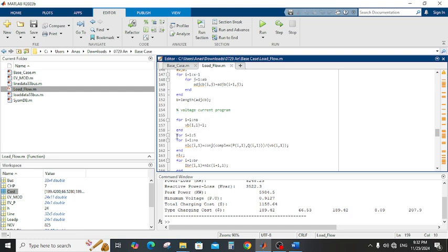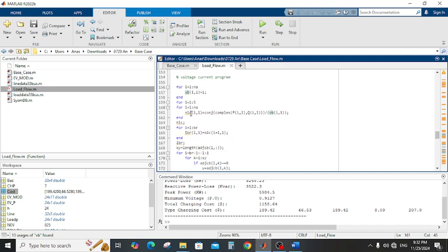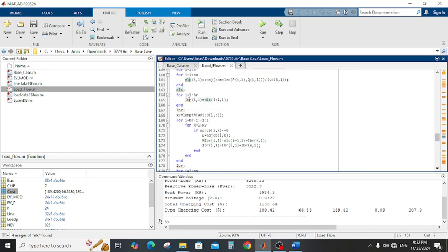After that we start the loop to calculate it. The first step depends on the real power and reactive power in that hour divided by the bus voltage that we assumed in the first step, 1, to calculate the net current from each bus. After we calculate the net current for each bus, we start to calculate the branch current.